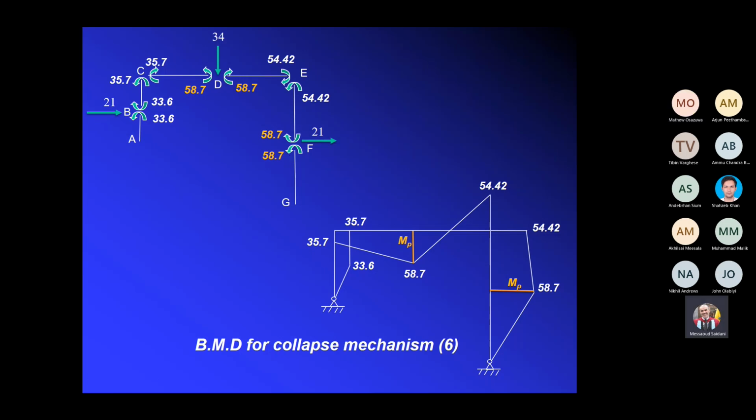Take a ruler, if you have a ruler, and bend it with an anti-clockwise moment this way, and tell me, do you think the tension is on this side here on the right, or is it tension on the left side? It should be on the right. Exactly. So we've got tension on the right here, okay?